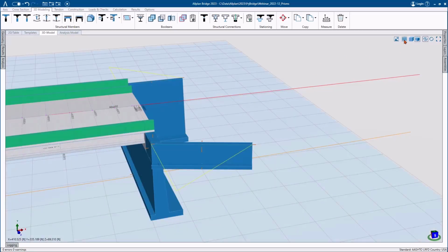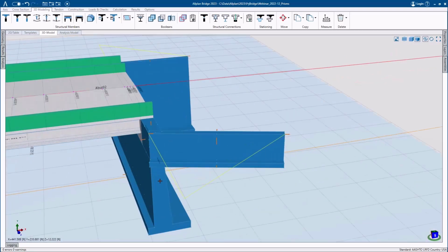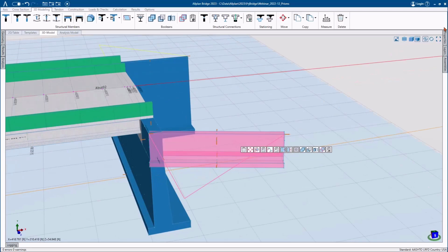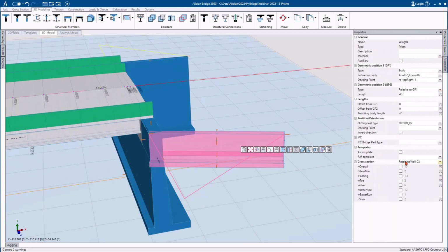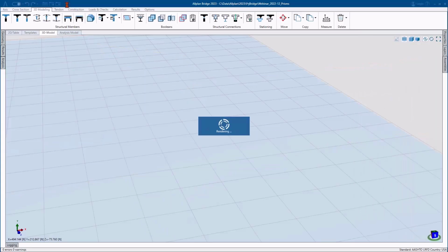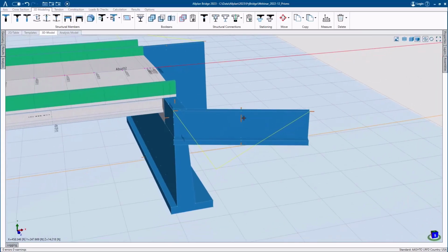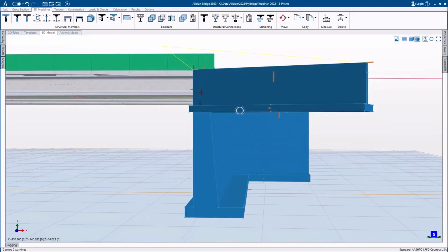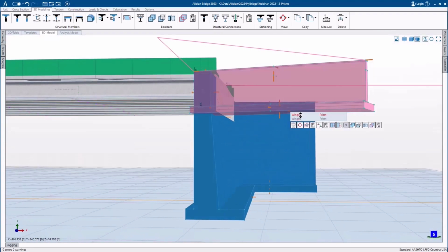So now it's at an angle other than a right angle to the abutment wall. We'll go ahead and specify that the thickness of the stem is 1.5. We'll choose a similar value for the width of the foundation. We'll recalculate. Now let's go ahead and stretch this into position here.